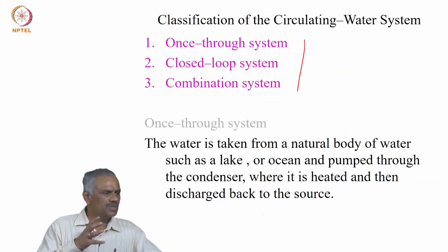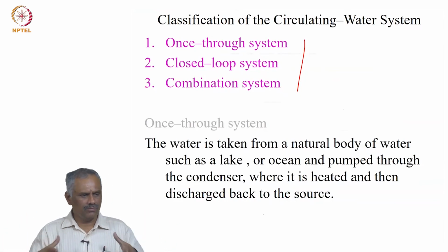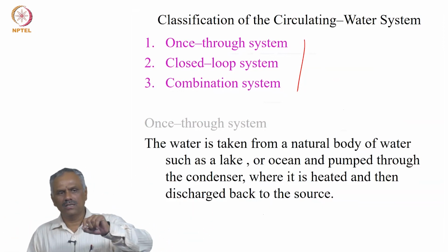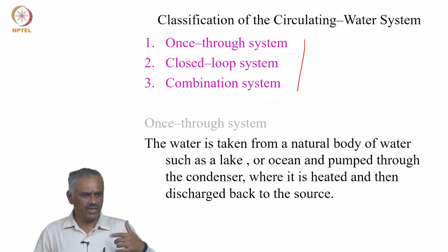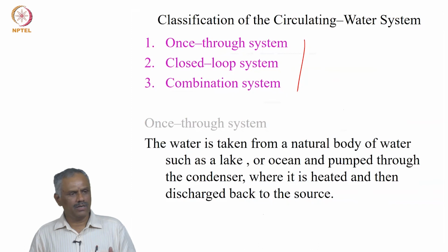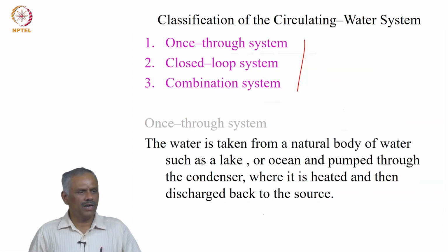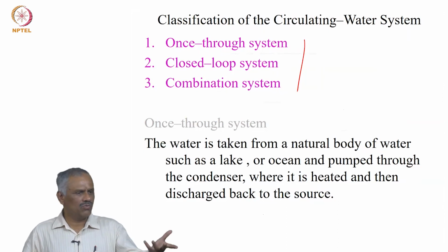You circulate water, because the pipelines and the cooling water pumps are very massive, since they are large volume pumps, and you are taking heat and then rejecting into the water body at a delta T of 5 or 8 degrees. But if it is inland, for example, you have a power plant in Rajasthan, Jodhpur, where there is no water.